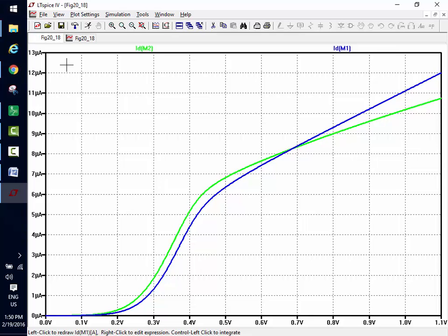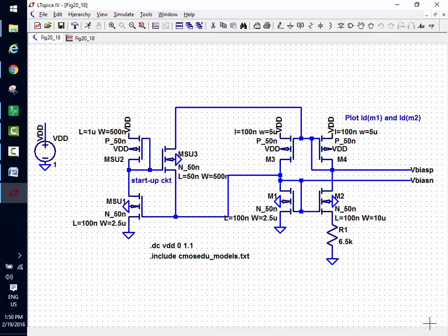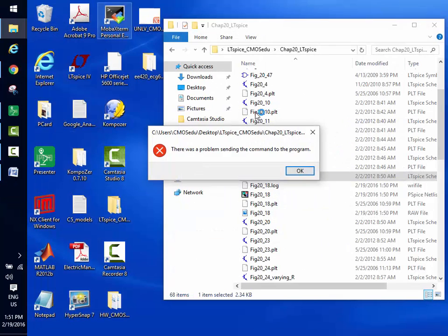So what if I look at the circuit and ask, how do I fix this circuit so things don't change with VDD? And the answer is I've got to ensure the drain to source voltages don't change with VDD. So if I could keep this voltage here at the same voltage as this voltage, the VGSs are fixed or tied. They're not going to vary with VDD. Then I can keep the currents through each side the same. So let me show you on the next schematic